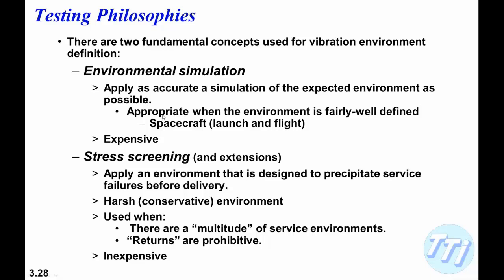This is appropriate when the environment is fairly well defined, as in spacecraft launch and flight. The problem with this is that actual simulation of the environment is relatively expensive because it requires programmable shakers and excitation systems that actually do precisely what you want them to do.